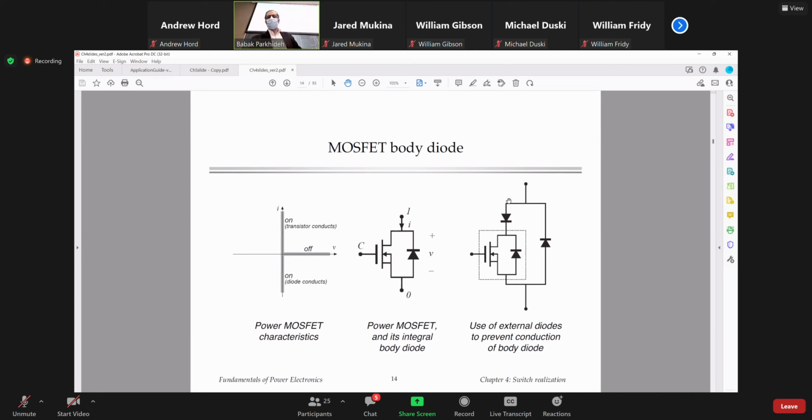But this particular diode, when you apply a certain voltage here to be blocked by these switches, let's say 100 volts, this 100 volts is blocked by this MOSFET. So this diode only blocks the current, but not the voltage. In other words, this is a very low voltage diode.